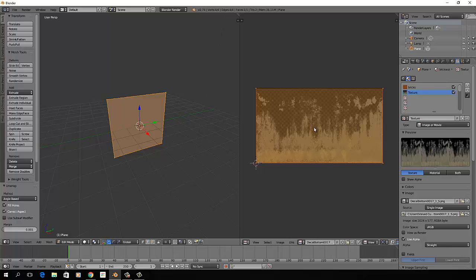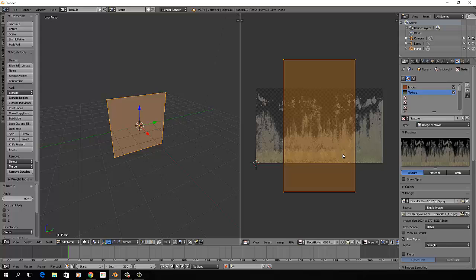So first, let's get our UV map turned the right way. I'll hit R for rotate, and I'll type in 90 and enter. That will turn our UV map on its side. I'll then hit G for grab and just move the map so that my decal sits at the bottom. Last, we want to size the UV map to fit this decal in the X coordinate.